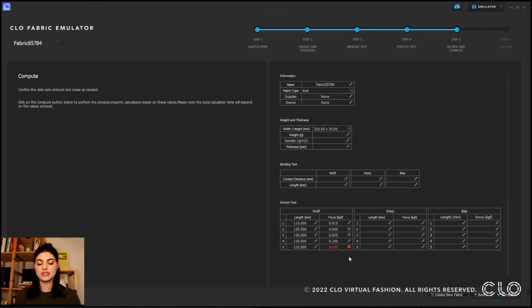This little information icon, when hovered over, will just state that this is counted as a very high stretch fabric. If the difference is above 0.005, then just that little tool icon will be next to it. And if the difference is below 0.005, a little warning icon will appear next to it, just letting you know that this is below what it should be, and maybe for you to check it out. Just always trying to be helpful.